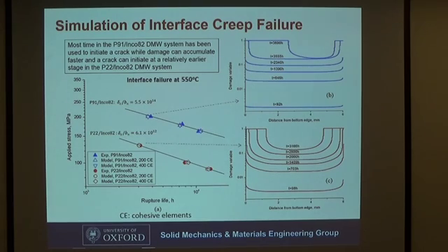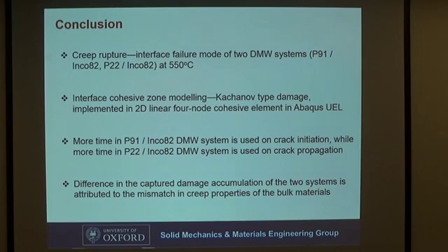Remember I told you the creep mismatch of the two systems. Oh yeah, good. So the main cause is due to the creep mismatch between the two materials. The larger the creep mismatch between the two materials is, the more likely the crack will initiate at the early stage.